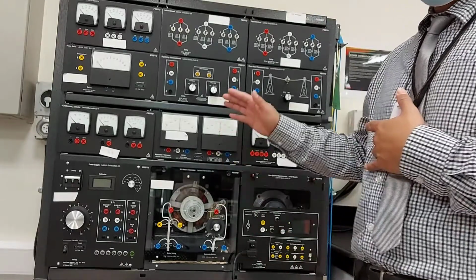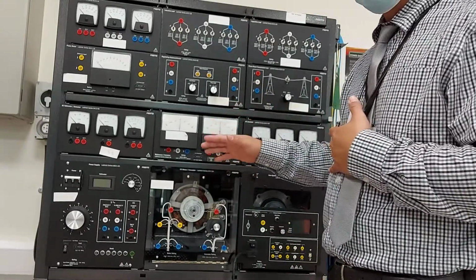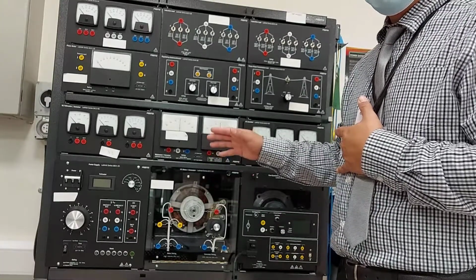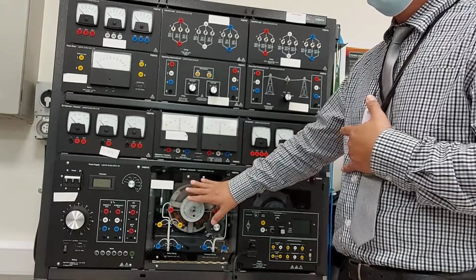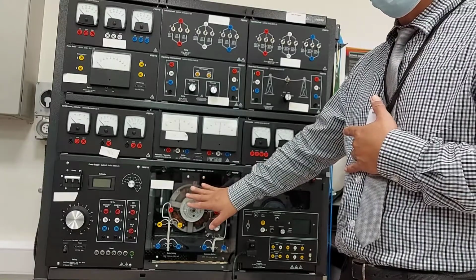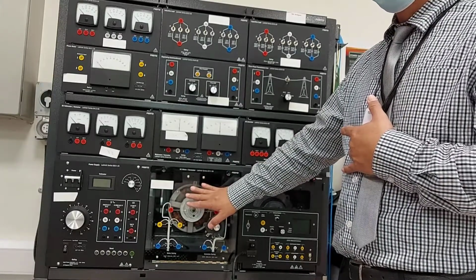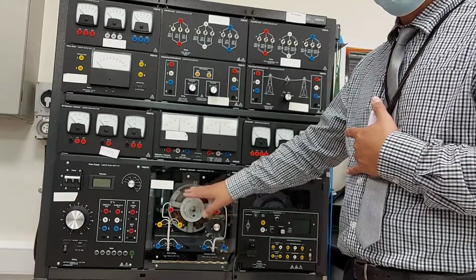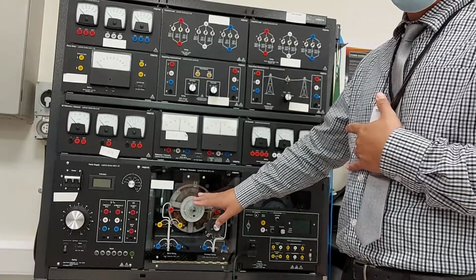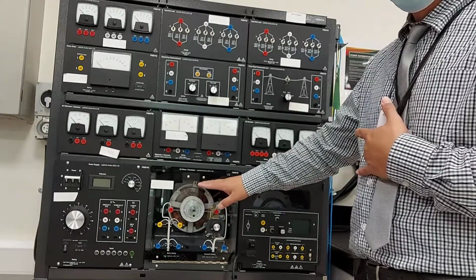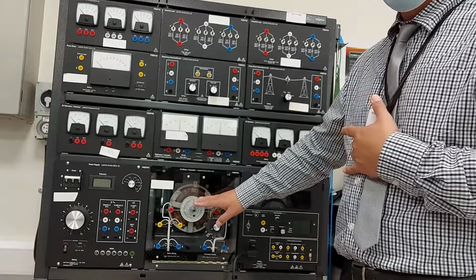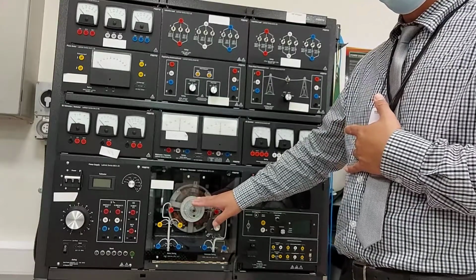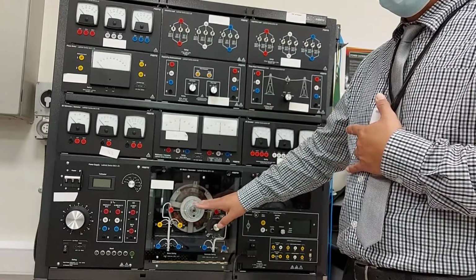Pay particular attention to the motor, rheostat, connection terminals, and wiring. Note that the motor housing has been designed to allow you to view the internal construction. Most commercial motors do not have this open construction. For step 2, view the motor from the rear of the module. Identify the armature windings, identify the stator poles, and count how many stator poles there are.